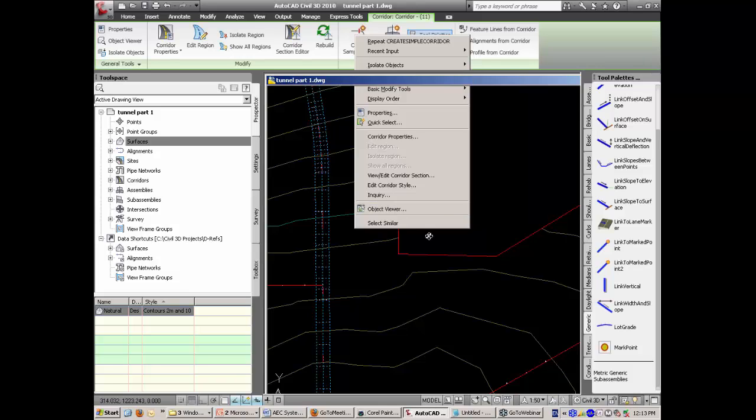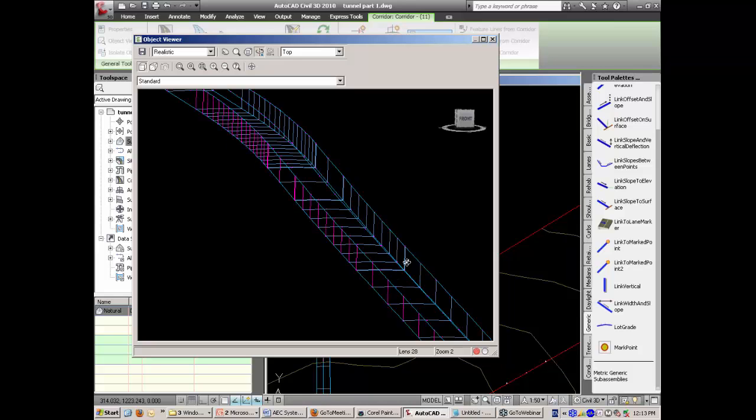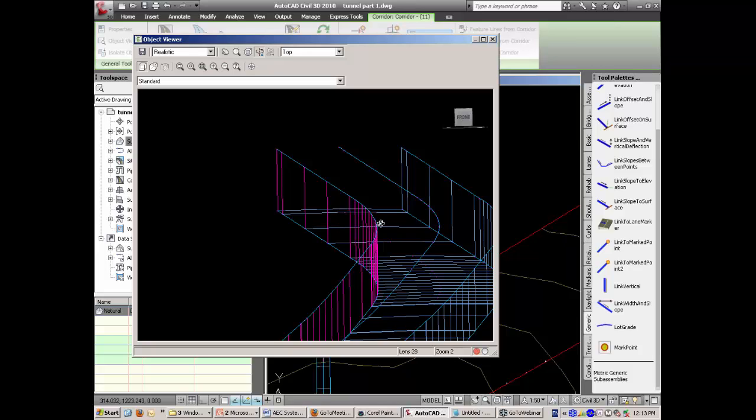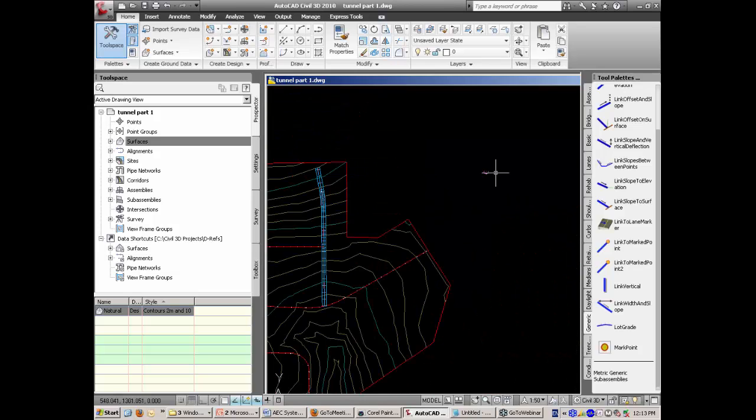Now if we take this assembly, I'll take this corridor model and look at it in the object viewer. Now I'm just going to zoom in. I'll pause when I zoom in and we should see what's happening. So when your screens catch up, what you'll see is we've got basically the horizontal road with the walls each side of it and a reference point in the center line. What we now want to do is create the roof. And the way we want to set this up is that if we widen the road, the wall and the roof come with it. Otherwise it isn't much use to us.